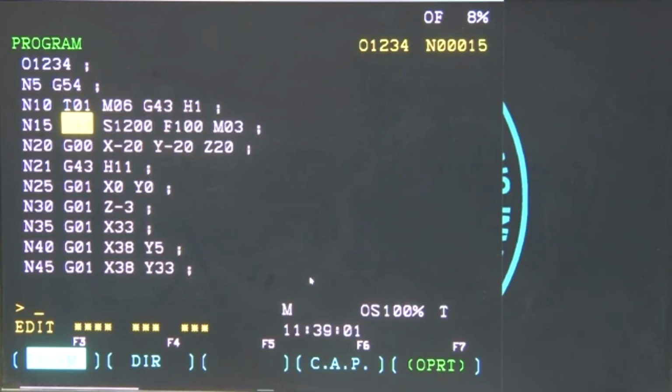If you remember, in the case of turning, it was revolutions per minute, it was the N, and the feed was given in millimeter per revolution. Here this is the milling cutter, so the feed has to be taken in millimeter per minute. So, this is G94, and S1200 stands for the RPM of the tool. The tool is 12 millimeter diameter, and for the aluminum we have selected, that RPM will be 1200, revolutions per minute.